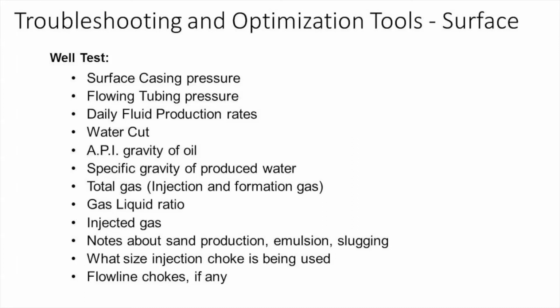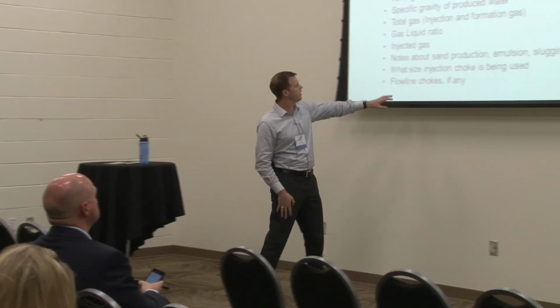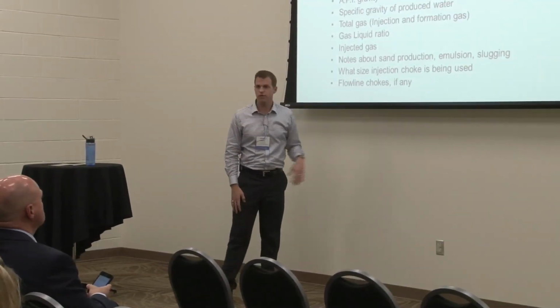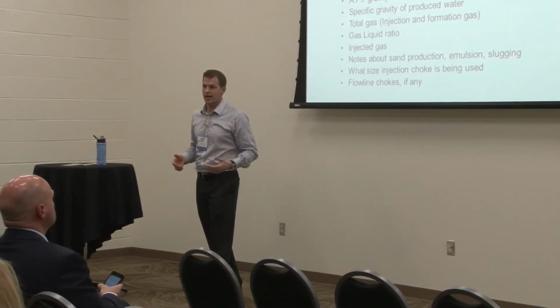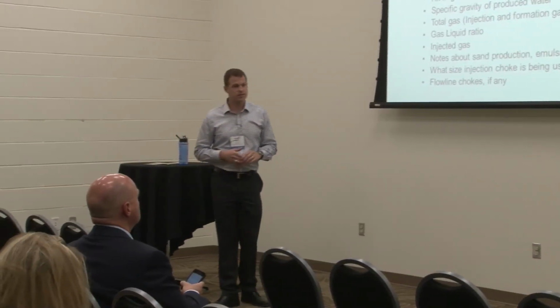Making notes about sand production, making notes about paraffin. Paraffin is a big issue. Salt buildups, hydrates, those kinds of things. And really looking at or getting an inventory of what you have out on location: flow line chokes, choke sizes, flow line sizes.